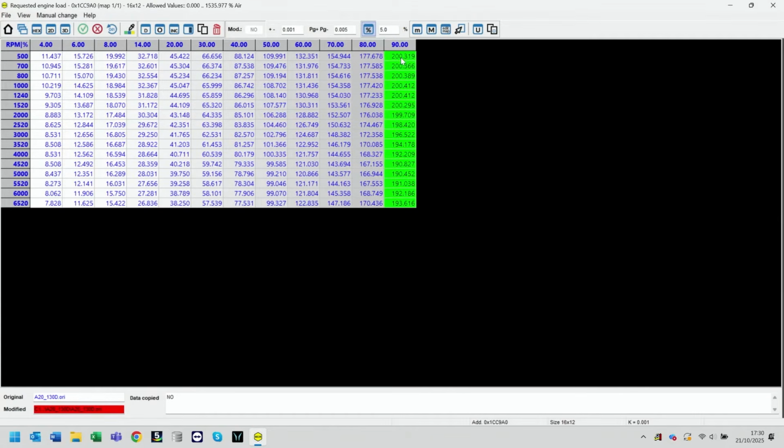We can put this up a little bit higher, and we're going to make a change by edit map, and we can put this up at 220 to keep it nice and happily out of the way. Yeah. It's not a value that's too high that's going to cause the ECU problems calculating. If we put 1,000% in there, yes, it's a great big number and it's way above our limit, but the ECU isn't going to really understand that value. It's not going to be able to achieve it, and you actually can have a problem the other way, where the ECU can throw limp codes or fault codes because it couldn't achieve the target that you asked for.